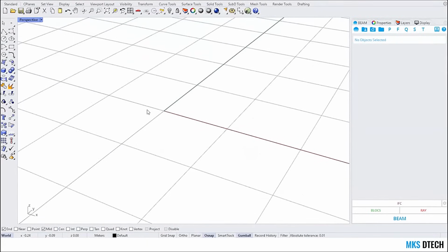What we're seeing a lot happening, since this blocks workflow is really powerful, is that a lot of users are using a specific folder or a library of Rhino models and using this as a family environment. They model the block in Rhino and then import with blocks to replace all the blocks in a facade or in a project. What they're building is a library with all the blocks in Rhino, with the right names, and basically just an object almost per file, and they have these nice libraries.